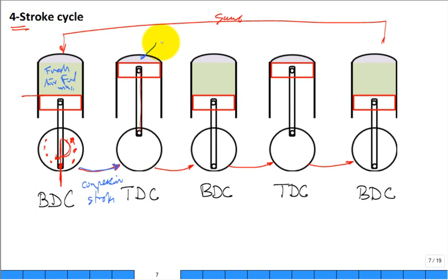And anyway, for here, that change going from the air-fuel mixture to combustion products is pretty fast. And we now have something that's very high temperature, very high pressure. And when it goes down, it's going to be pushing and expanding, forcing that piston down. This is the only stroke you get power out of the cycle. Okay, so they call it the power stroke. And it's just like that boundary expansion work that you've calculated again and again. That's it. The integral P dV, yeah, that's it. That'll give you the boundary work to push down the face of that piston.